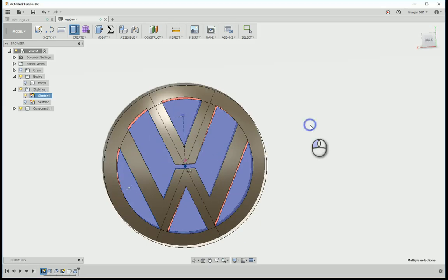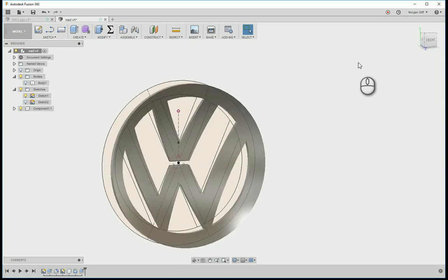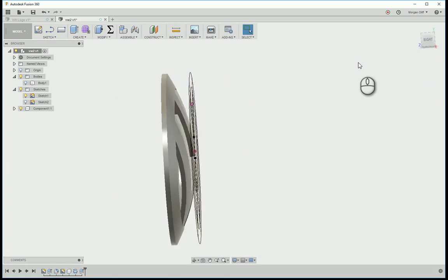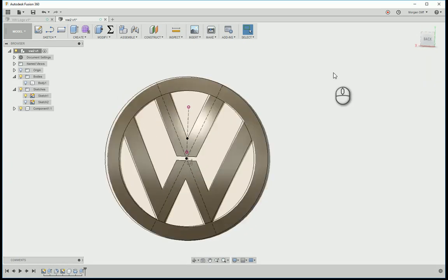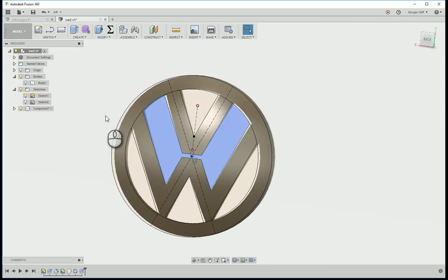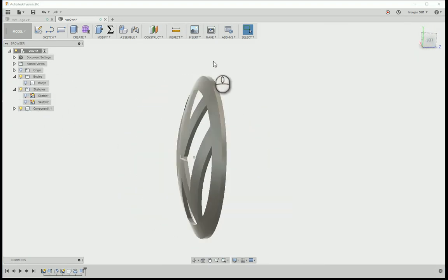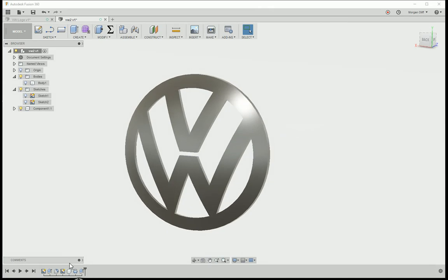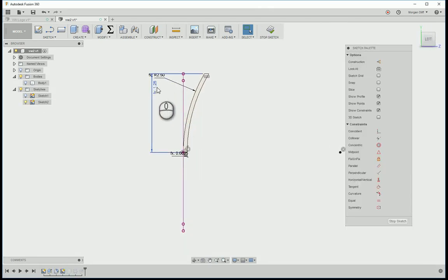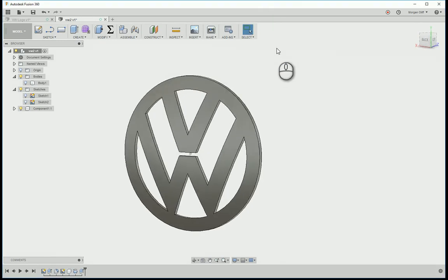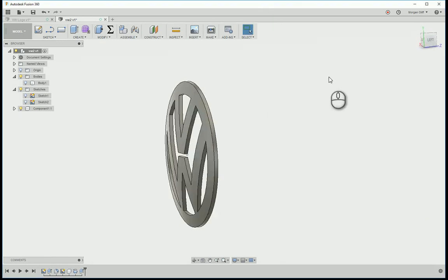So if we click distance all cut, we have this conical, it's a little bit not even conical, convex shape here. And so that's how we pulled it up. But let's look at this original sketch because I don't like that. D1, let's go ahead and make it times 2. And that flattens out the curvature there. That's a little bit more realistic. Even that's still too much.